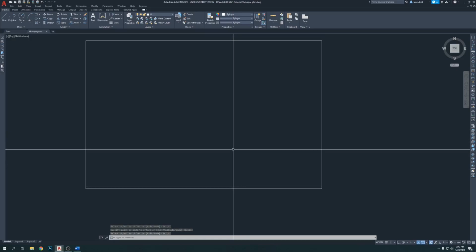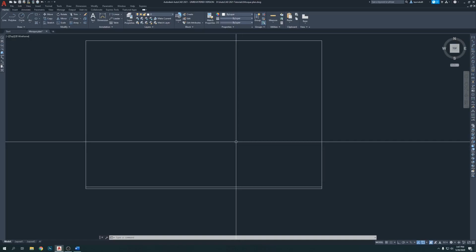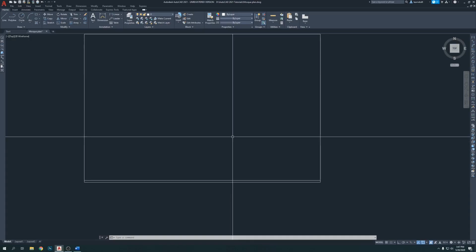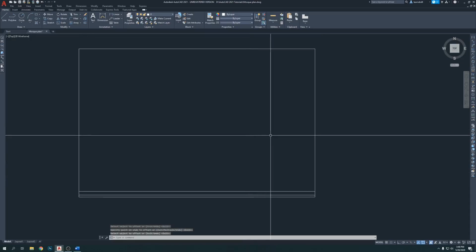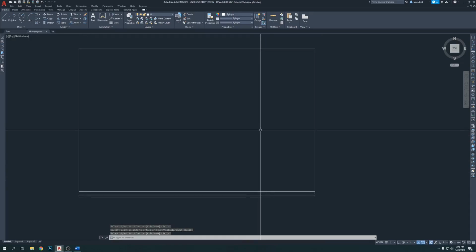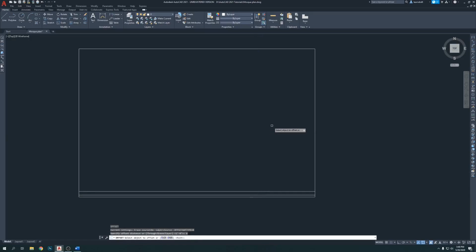Now we're going to have 1 foot. Sometimes we put shoe boxes. Sometimes if somebody stands up, they need some space behind them. So let's say 1 foot offset. Enter. 12. Enter. So from this wall, 1 foot inside. Now the same way on both sides. Offset. Enter. 6 for the wall, 6 for this wall, and then